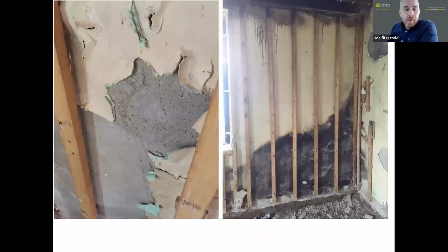So likewise, a very poor understanding of dry lining came about around the same time. And in this instance, what happened was an old farmer tried to just make his old kitchen a little bit warmer. So what he did was he framed the wall with some timber right over his gypsum plaster, which sat on top of, in some cases, mass concrete and in some cases block. And he filled that old dry lining with a small bit of insulation, like a mineral wool or something like that, and then he put plastic sheets over the whole thing, and he didn't really tape them up.